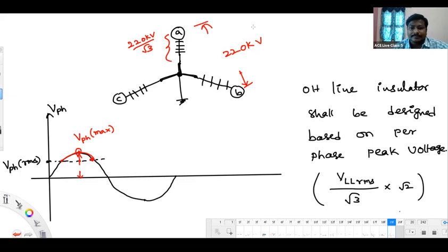Yeah, next thing. Actually, Bhavani, after applying this voltage, the insulator will experience a voltage stress, or you can say electric field intensity also. If that value is greater than the dielectric strength, the insulator is going to be damaged. That's the problem we are discussing now.